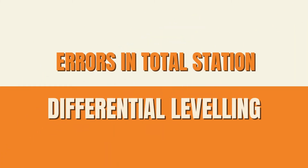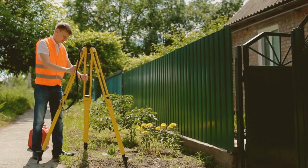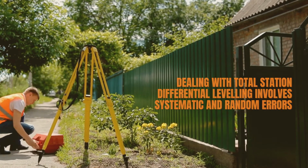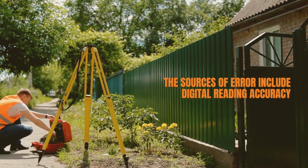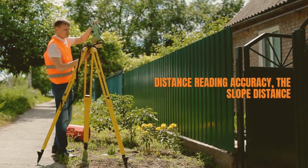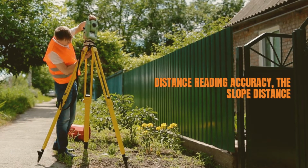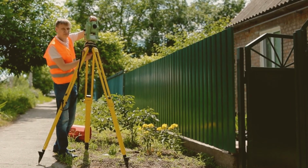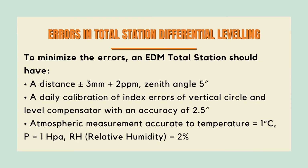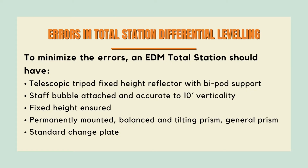Errors in total station differential leveling. Dealing with total station differential leveling involves systematic and random errors. The sources of error include digital reading accuracy, vertical automatic compensator error, distance reading accuracy, the slope distance, setup accuracy over the measuring point and target point, centering accuracy, and the accuracy of height of instrument and target. To minimize the errors, the following are listed below for an EDM total station to have.